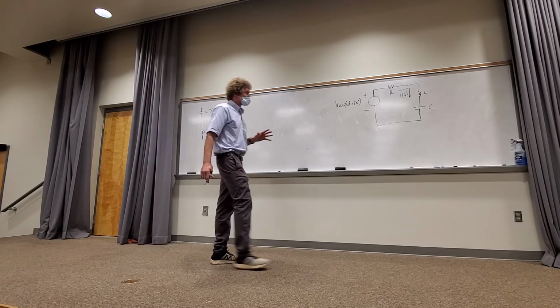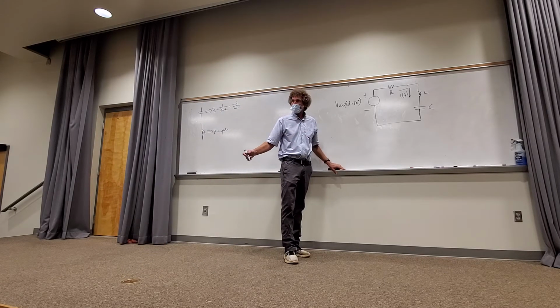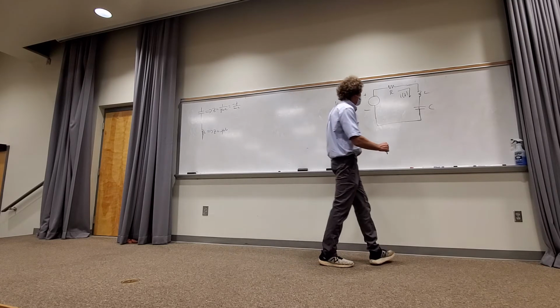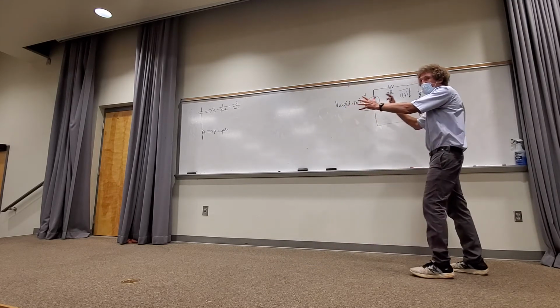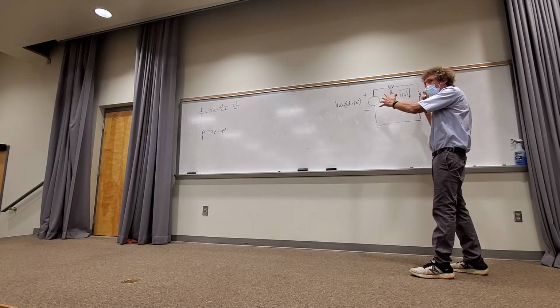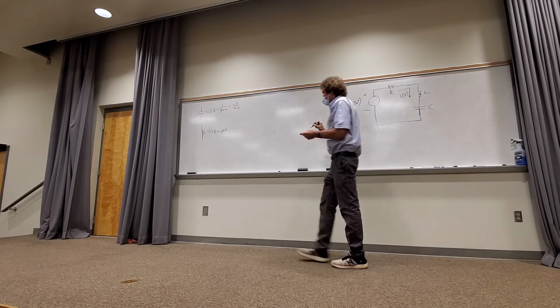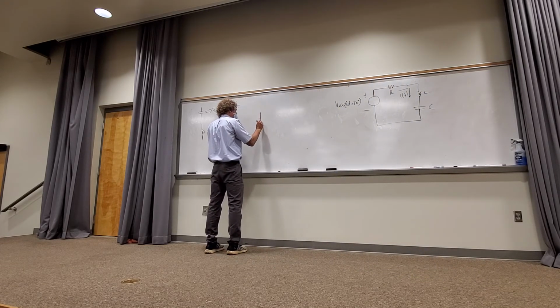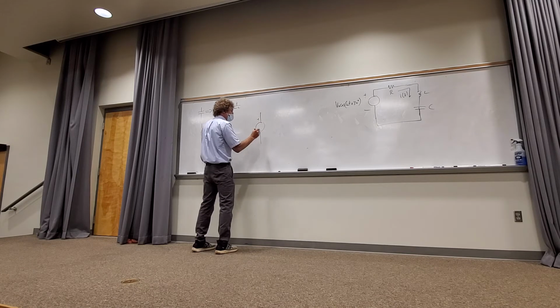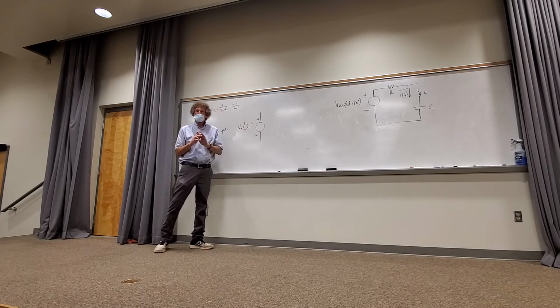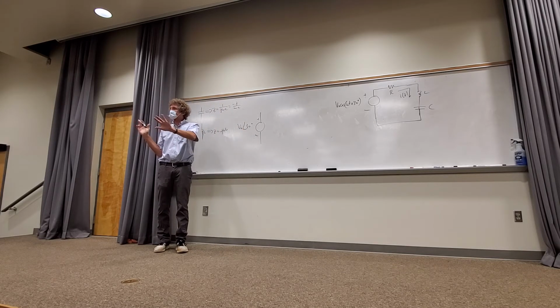Now, getting back to this, here's how we solve this. You ready? This was in the reading. If you looked at your books this weekend, this was exactly what I showed you to read in the book you purchased for this course. So what happens here is, we take this problem and we go out of the time domain and into the frequency domain. You see this right here? That source becomes this. It's just going to be V naught at an angle of 30 degrees volts. No cosine business. All that's suppressed.